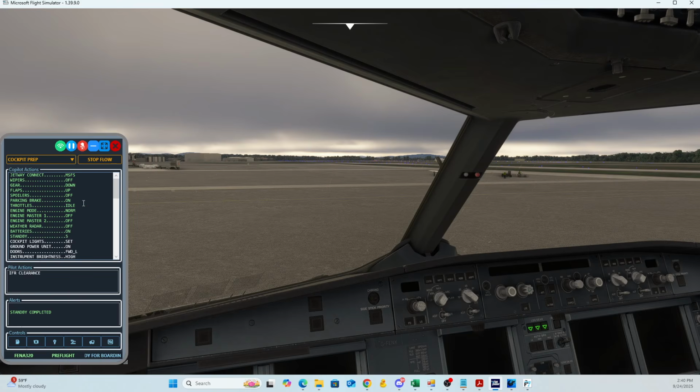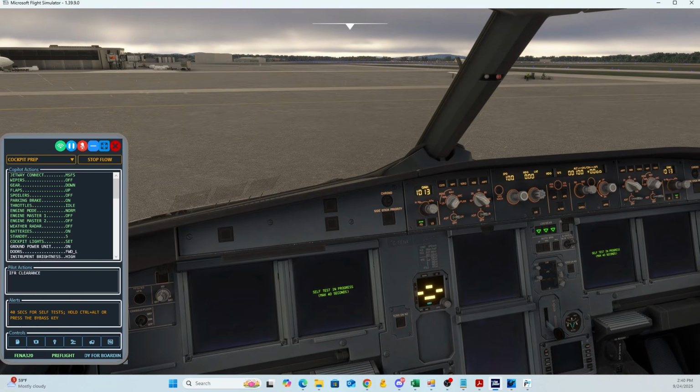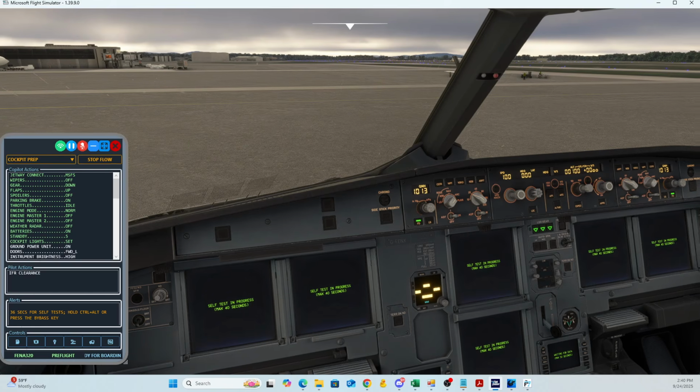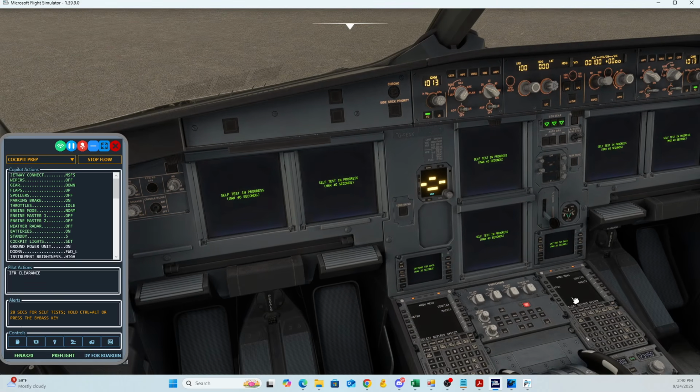As you can see here, first flight of the day, so we did his safety checks. Now he's coming down and he's going to go ahead and start the power, which he just did, and now 45 seconds for the self-test. After he completes this, you can see that the forward left, we have the co-pilot opening the doors for us, which will be accomplished via the MCDU.